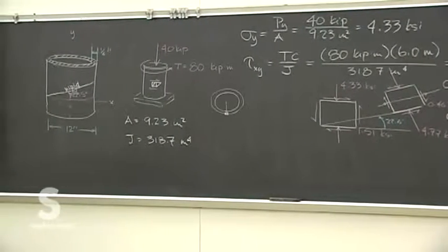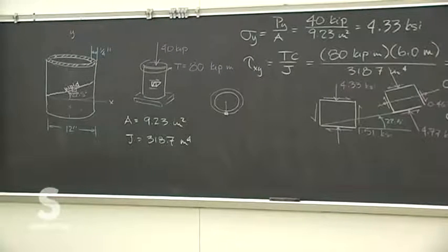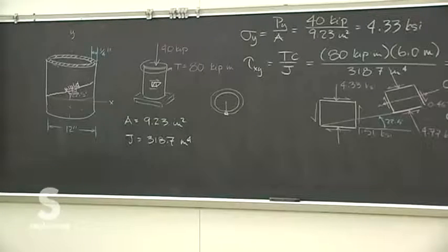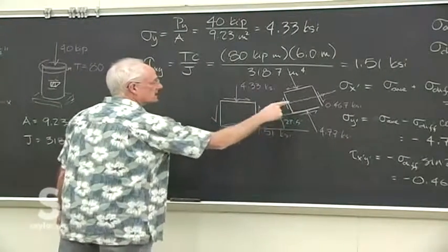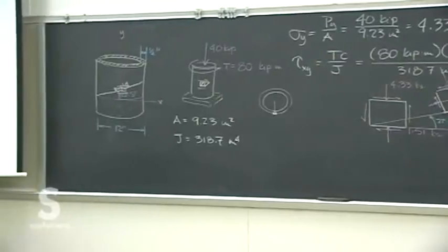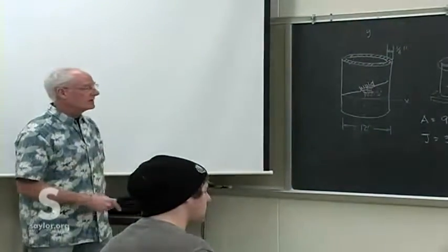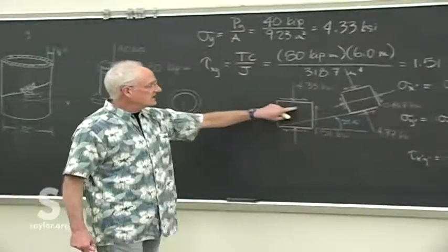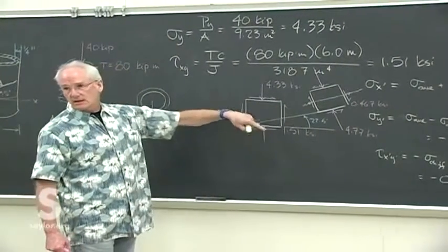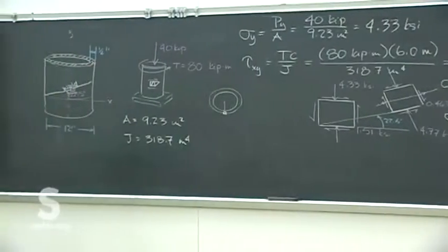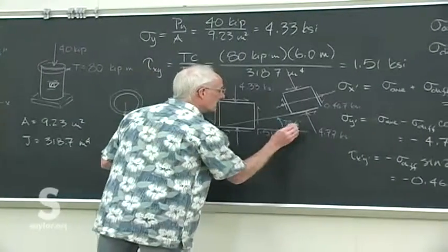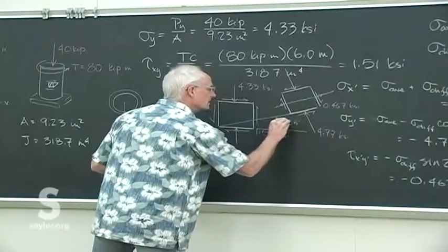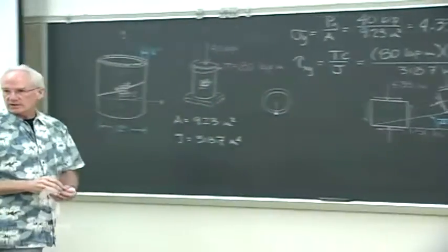Okay. No reason on this one to draw a Mohr circle. There's no great value in it, but you can if you want. It'll just show you the same thing we got here. It'll show you where this point was, and then we moved 22.5 degrees off of that, which is not the same as going from the point A that we've plotted before with these values to the x-axis, the normal stress axis. That's the principal angle. That's not what this is. This was just an angle that was of concern because of the way the piece was constructed.